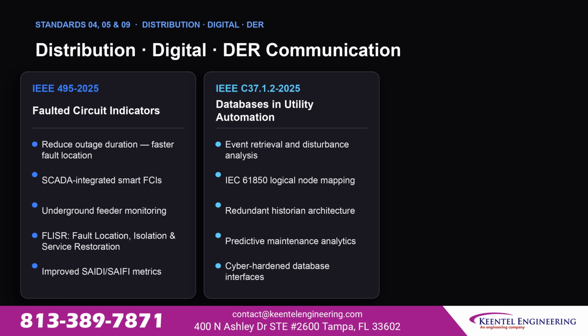IEEE C37.1.2-2025 addresses database architecture in utility automation. Digital substations generate massive volumes of event and operational data. This guide defines how to structure, retrieve, and maintain it, covering historian architecture, IEC 61850 logical node mapping, and cyber-hardened database interfaces that feed faster disturbance analysis and predictive maintenance.